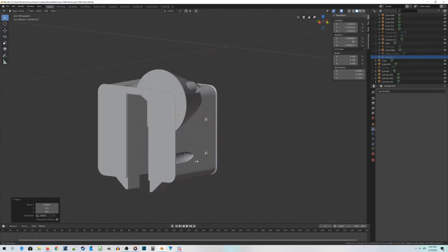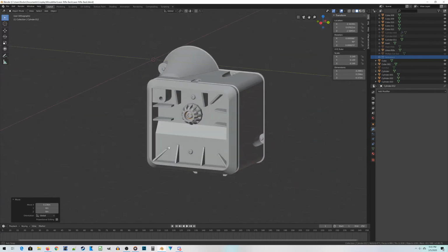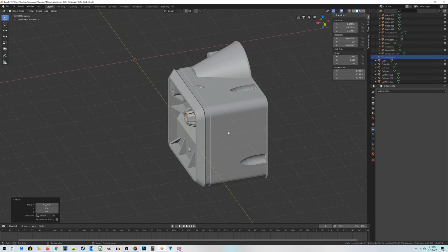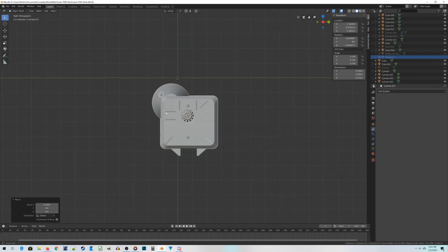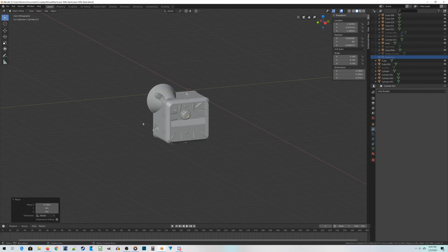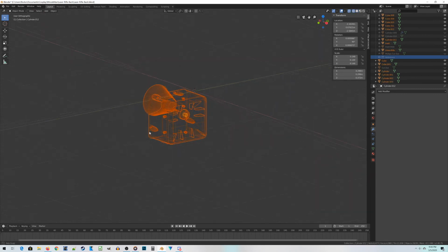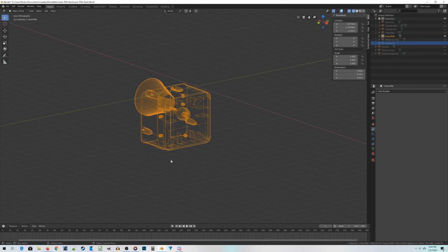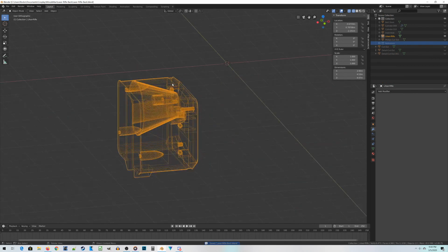The last thing we need to figure out is just how big it has to be. Of course, that depends on exactly what cosplay piece you're attaching it to, but let me show you how you figure that out. First things first, you want to join everything together into one giant object. So switch to wireframe, do a box select for everything. Let's make sure that guy's a primary because why not? Control J. Now everything is one gigantic object.